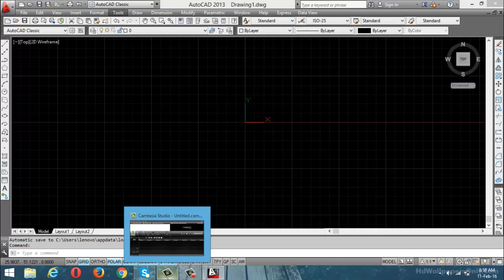Now see, this 10 is nothing but a linear value. Again you can see the direction. This is 0 degrees, 90, 180, this is 270. Same thing. Now what type of design is this? Line. For that purpose I am going to select the command L enter. In the same format I am going to choose the start point as 3 comma 10. First point, starting point is your interest. Then I am going to define the next point by using one linear value and one angular value.